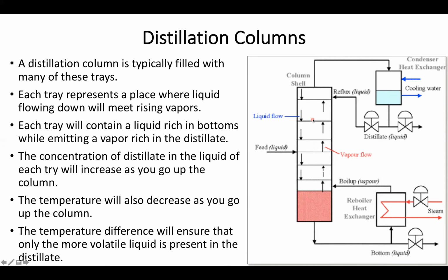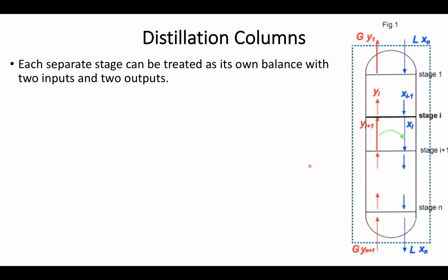So it's worth noting that if you're really going to model a good distillation column from a chemical perspective, what we typically do is what we did last semester in PChem and use a multi-phase diagram to figure out the ratio of distillate to bottoms at each of these trays. And this is exactly one of the ways you can examine the distillation column: by finding the separation at each tray and performing a mass balance, figuring out how much of the liquid will fall and how much of the vapor will rise at each stage.